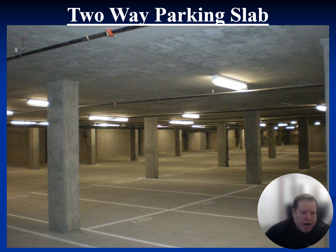A note, at the top of the columns, at these floor levels, we do not have caps or drop panels. We are using stud rails for punching shear resistance. I'm a big fan of stud rails to resist punching shear, excuse me.